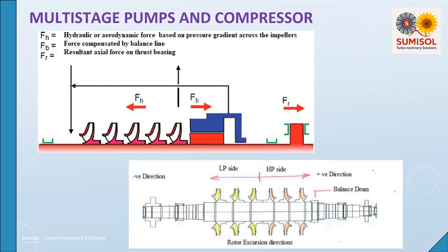Axial thrust monitoring in multistage pumps/compressors is vital for preventing bearing failure, using methods like thrust balance devices, drums, discs, balance holes, back-to-back impeller arrangements, to counteract immense hydraulic forces, monitored through shaft position sensors, proximity probes, and vibration analysis to detect imbalances from design changes, fouling, or operational upsets, ensuring reliability by comparing actual thrust loads to predicted loads.